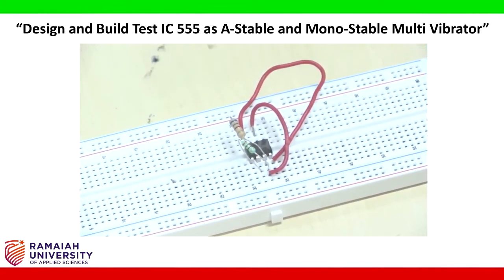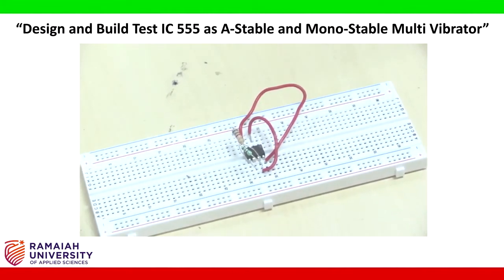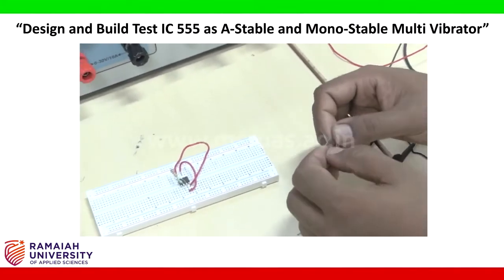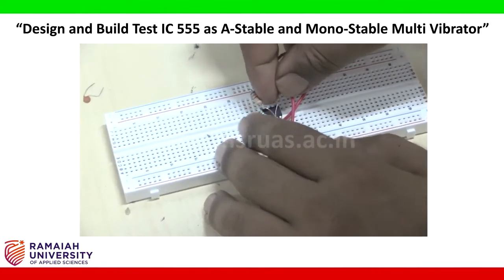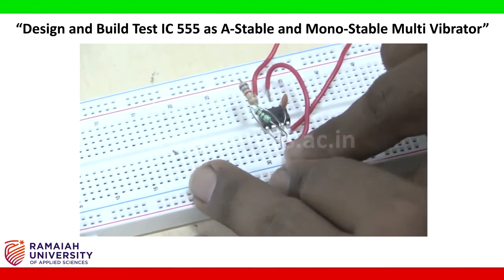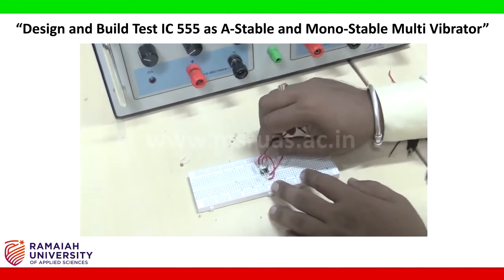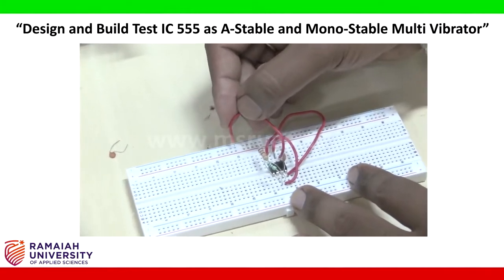Next, pin number 5 and 1 will be connected with a 0.01 microfarad capacitor. So this is the 0.01 microfarad. I need to connect this capacitor in between 1 and 5. So this is my pin number 1 and this is pin number 5. See here, the capacitor is connected to pin number 5 and to pin number 1. I will connect pin number 1 to ground. This is pin number 1 and that will be connected to ground.